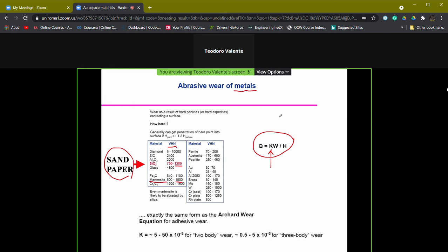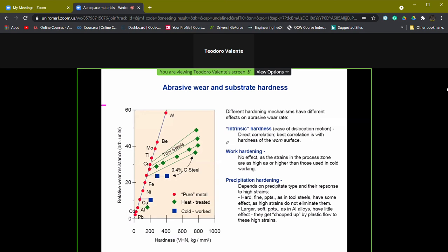But also in the case of abrasive wear, apart from the consideration on the normal load, the general equations tell us that an increase in hardness of the weaker surface is able to reduce the volume of material which is consumed per unit time and unit length of sliding. This applies also for adhesive wear, and it was the slide that I was looking at before.